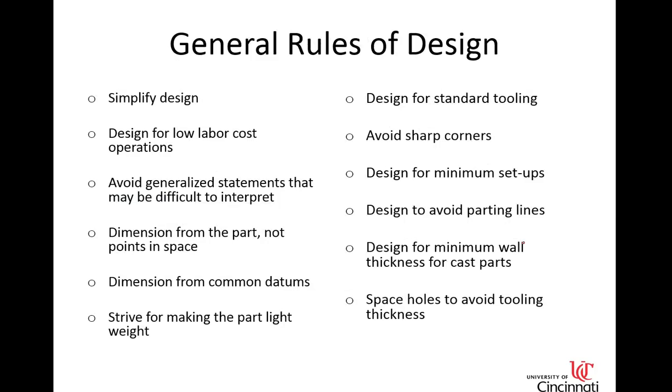So general rules of design, for those of you who haven't had a design class yet, this might be new. These are good rules of thumb, I'll let you see these in the slides, but some I wanted to point out. Design for standard tooling. That's a common thing that I talk about in my manufacturing classes. Don't come up with funky shapes just for the sake of having them. If you're going to have a weird, non-standard tool shape, make it be for a good reason. Otherwise, go for the standard.